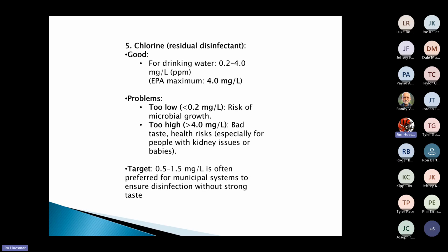Lastly is going to be chlorine. Chlorine is, I don't want to say it's good for you, but we have to have it in the water. That's what's going through and helping sanitize, killing the bacteria levels and everything else. But when we start getting to a low chlorine rate, we have a lot of microbiota. We have a lot of growth inside those lines.